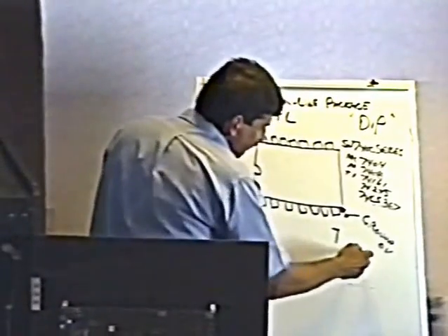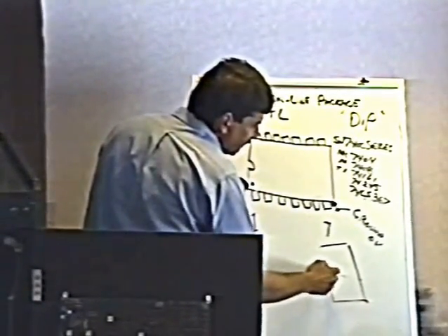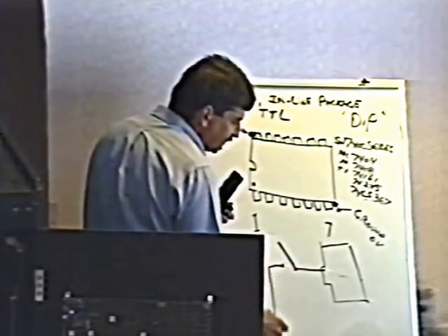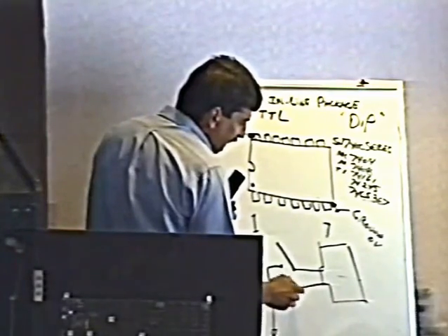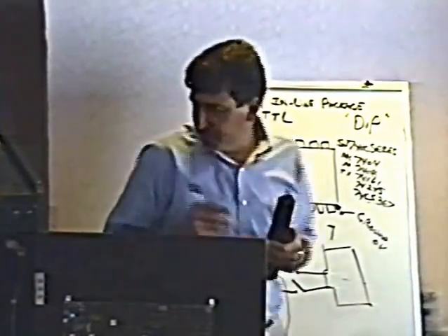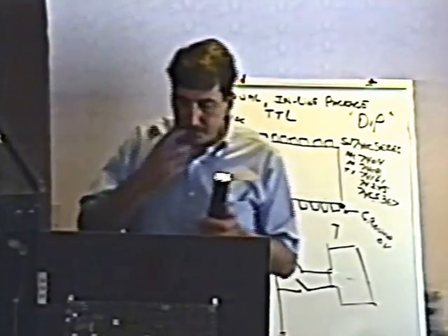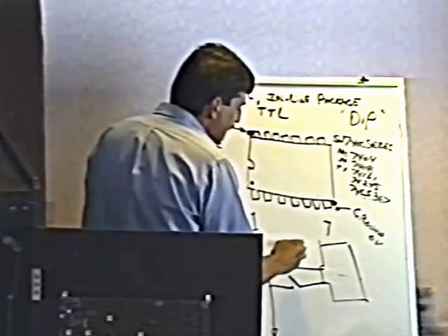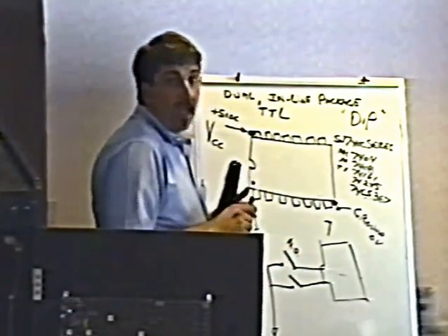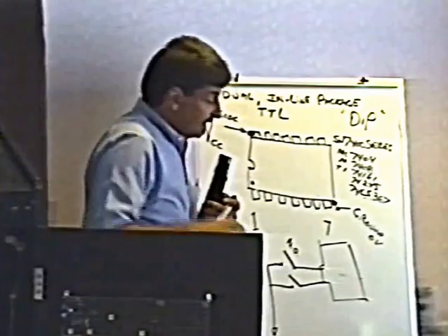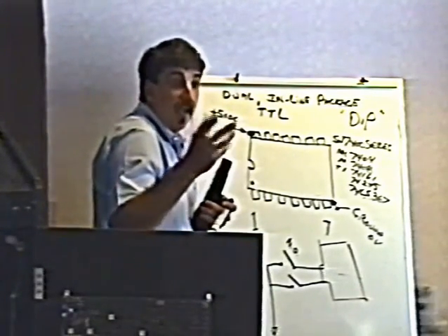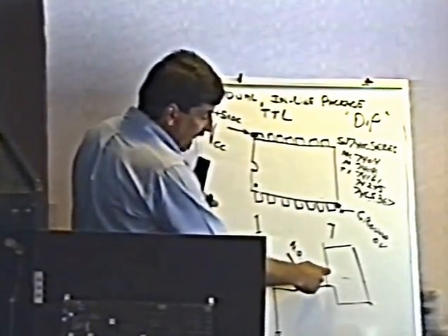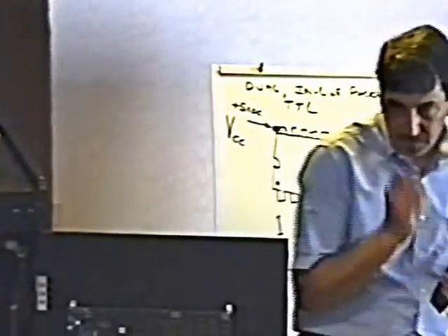In a video game, you have the logic board, as you see in the drawing on that page. And the logic board is connected to the switches which are in the control panel of the game. Those switches are what we call normally open switches, abbreviated NO, meaning that when you're not pressing the button, the switch is not connected. It's open. What that means is that we've got quite a long wire from the logic board up to the control panel.